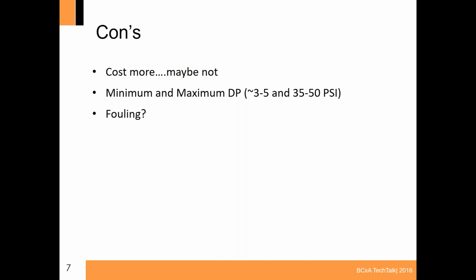And then the other one, when the pressure independent valves first came out in the design, there was a major concern about fouling, right? You don't have your typical characterized ball valve that opens up and small elements within the system, if we haven't flushed it out and cleaned it out, they just keep blowing by. In the older designs for the pressure independent valves, there were a lot smaller orifices that it was going through, and they were susceptible to little bits and pieces getting stuck in there and fouling, and then it would basically take away from that pressure independent control.